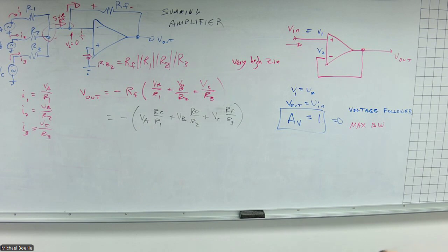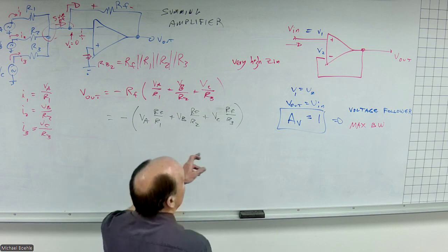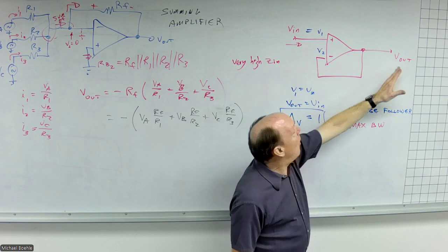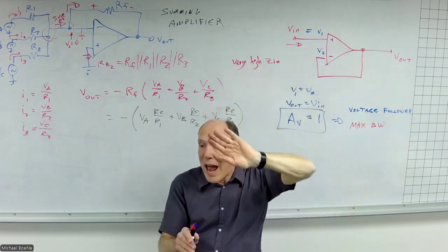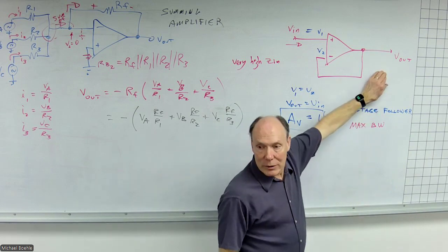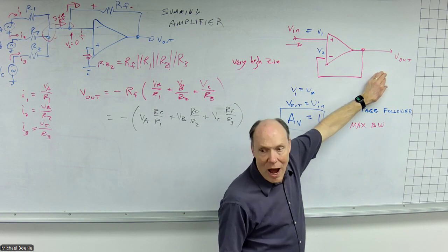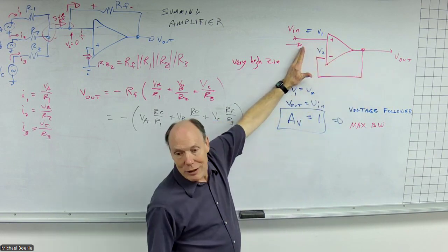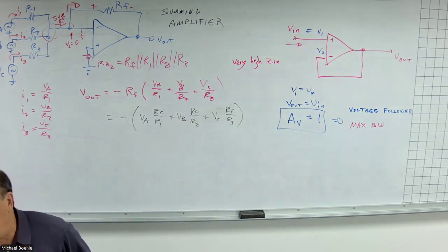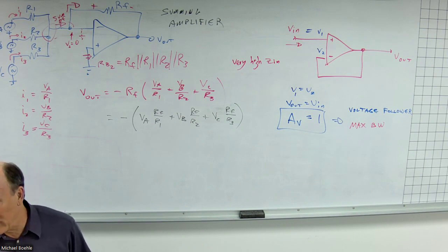If I hook this up to, say, a voltage divider, there's no load on that voltage divider. I don't alter the value. But I can use whatever that voltage coming in is going to be that voltage coming out. Now, because the op amp is being powered, it can drive current. I can draw several milliamps out of here to drive whatever I need to drive without loading the voltage divider. Very useful for that kind of purpose to go into other circuits. Think of it as a buffer, another way to look at it.